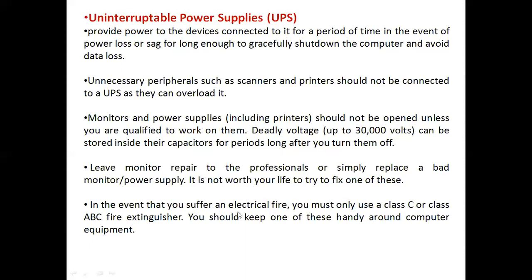In the event that you suffer an electrical fire, you must only use a Class C or Class ABC fire extinguisher. See, in exam, if there is a kind of objective question, they can ask, if there is an electrical fire, what kind of fire extinguisher is used. So always remember to handle electrical fire, always use a Class C or Class ABC fire extinguisher. You should keep one of these handy around computer equipment. You should always keep in your lab or in your work area where you are working on computer or computing equipment at least a Class C or Class ABC fire extinguisher.